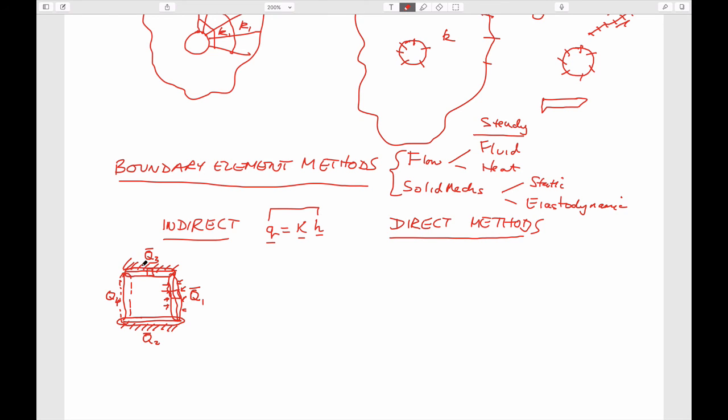So on this boundary, we're saying that the flow velocity is 0. And so that's something we know. So if you look at this, we know that the head on this boundary is equal to 1, say. I think that's what we're going to use. We're going to have the head on this boundary as equal to 0. No flow boundaries top and bottom. And so we're going to figure out exactly what the four values of Q would be that would give us these boundary conditions. So that's told us what the values of Q would be, but nothing else.